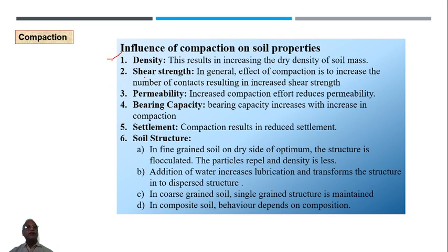So density is there, shear strength is there. These are the properties. Permeability is there, bearing capacity is there, settlement is there, soil structure is there. For every one of them I have made a statement. Density, it is obvious, this results in increasing the dry density of the soil. Obviously as you go on increasing the compaction, or just you compact the soil, what happens is there will be